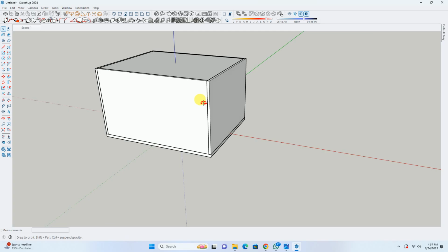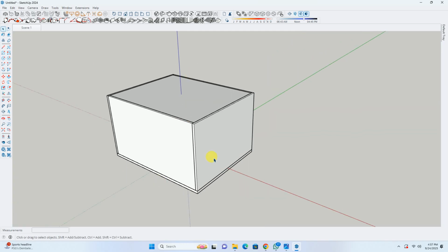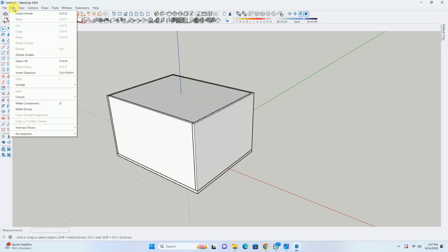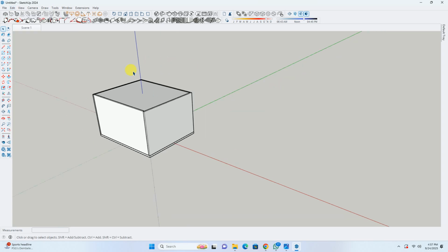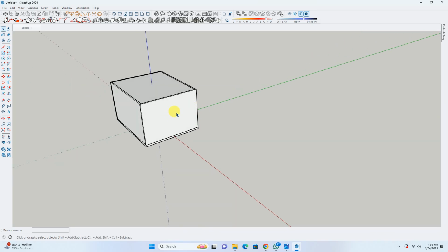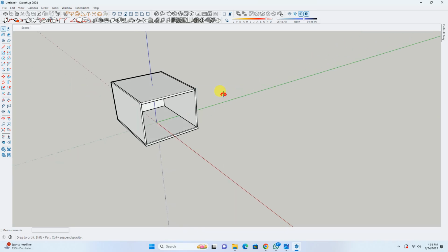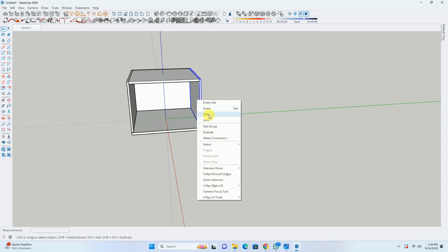By adding a scene, what are our advantages? Suppose we want to unhide all our elements, we can do that by going to the edit option, then the unhide option, and then unhide all. In this manner, all the hidden elements will become visible. Now, suppose I have applied the hidden feature to some other elements. I haven't deleted them.